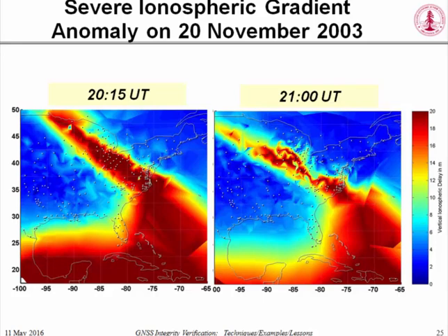Now the last fault I'll talk about is not based on GNSS, but based on the atmosphere. Typically, the ionosphere: signals transit through the ionosphere, and there are various things the ionosphere can do. It delays the code phase, advances the carrier phase, and we can correct that using dual frequency, which is what future RAIM users will do.